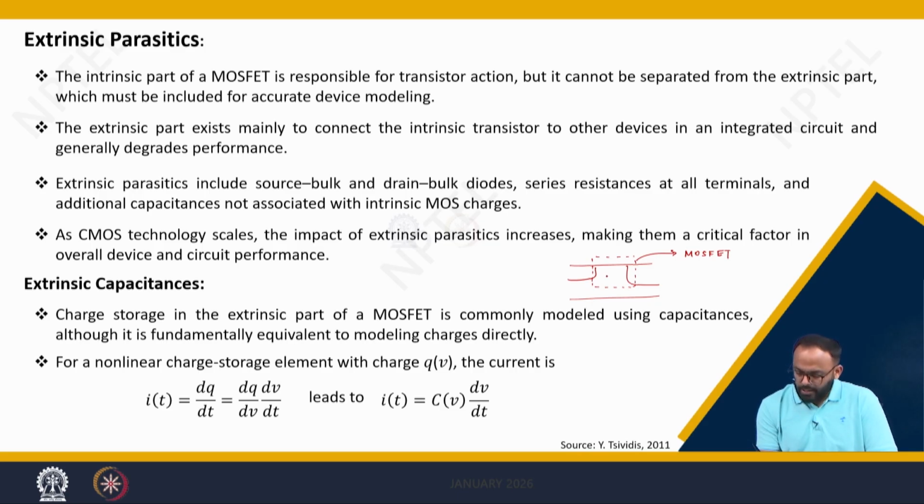The intrinsic part comprises inversion charge, bulk charge, gate charge, and substrate or body charge or oxide charge. However, when you put the MOSFET in circuits, the overall MOSFET operation will be limited by its extrinsic effects. These extrinsic effects, or extra effects, are called parasitics.